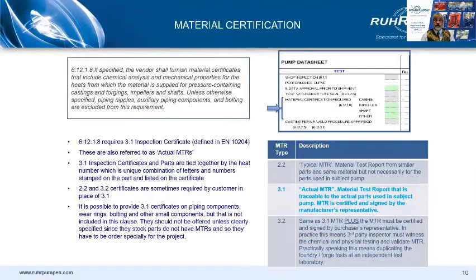Now, all of this costs time and money. So don't just think, that would be nice to have, and tick the box. Ask yourself before specifying if it is really necessary. Is it critical service, very high temperature, very high pressure? Is it worth the cost and lead time? Because it could easily add a month to the delivery time.